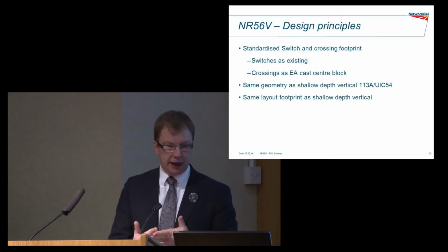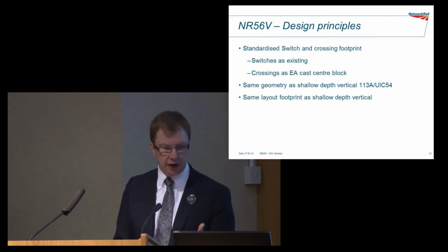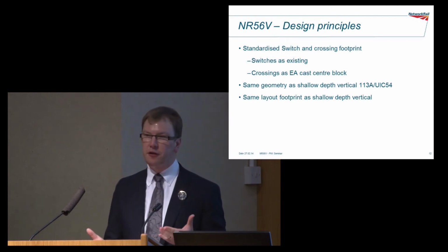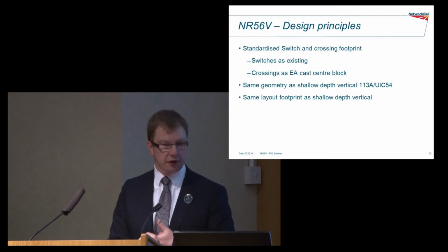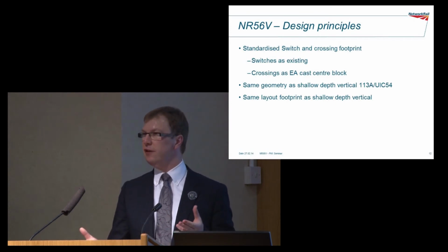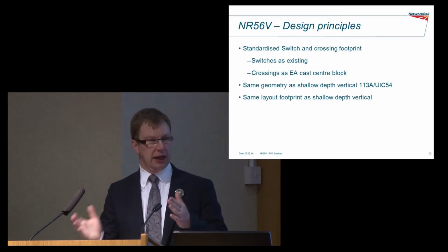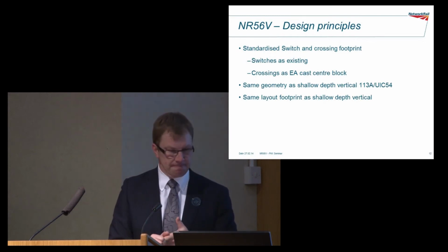So the basic design principles of NR56V. I've talked about standardisation and switch and crossing footprints. We've kept the same switch footprint as the existing shallow depth vertical. So an NR56V half set of switches can be interchanged with an old style shallow depth half set of switches.